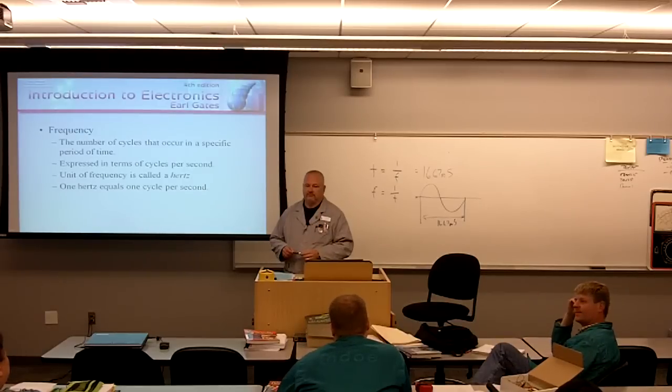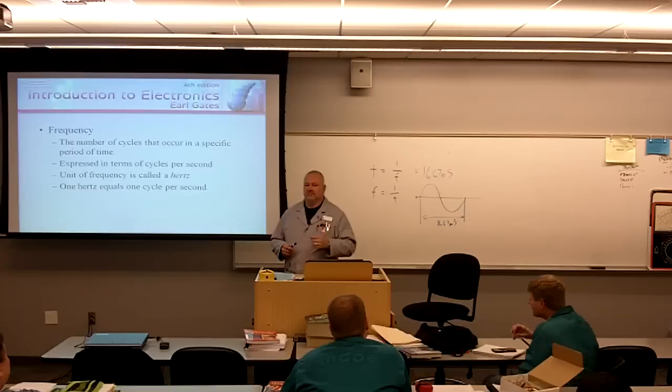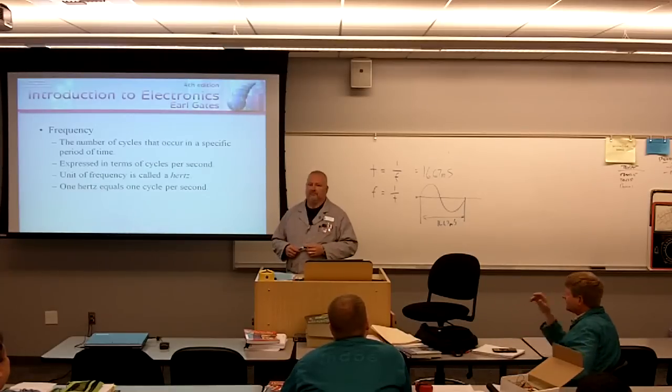So if you divide that by 2, which gives you about 8.3 milliseconds, that means that the lights are turning on and off every 8.3 milliseconds, right? When it goes from the positive to the negative, technically, but we just can't pick it up. And in Europe, it's 50 hertz, so that period of time is even more pronounced. But for an incandescent bulb, the filament doesn't cool down enough, though for some of these bulbs you will notice a little flickering, and some people don't dig it.